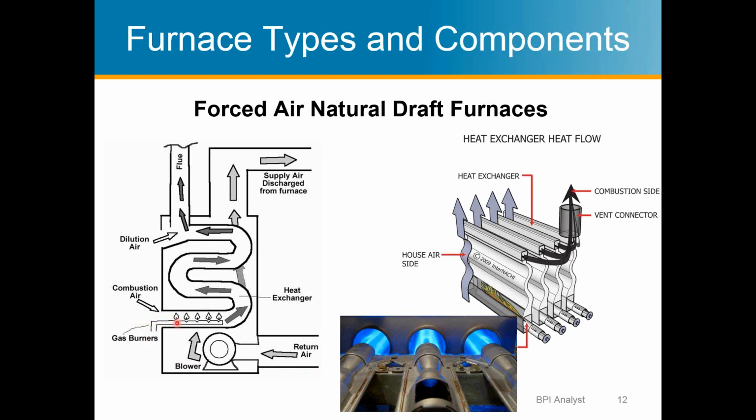So usually they shoot in, or they could be small flames here, but modern days they look more like rocket engines here that they shoot flames inside. But either way, the combustion is happening here. The gas and combustion burners are here, and the combustion is happening here. The heat and the exhaust fumes and all the exhaust gases stay inside this chamber here, and it just goes back and forth until it goes out the flue, and this is where that dilution air is added.